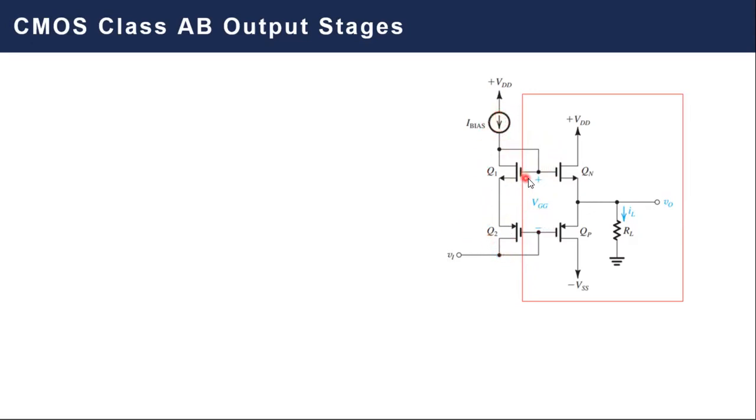The current flow, you know that there is no current flowing in the gate. So simply in this branch and in this branch, similarly here, no current flowing. So the I bias will move in Q1 and then in Q2. That leads to the I bias equals ID1, or the current flowing in the drain of the first transistor, which, again, we are now in a saturation region, so it's Kn' over 2, W over L, (VGS minus V threshold) squared.